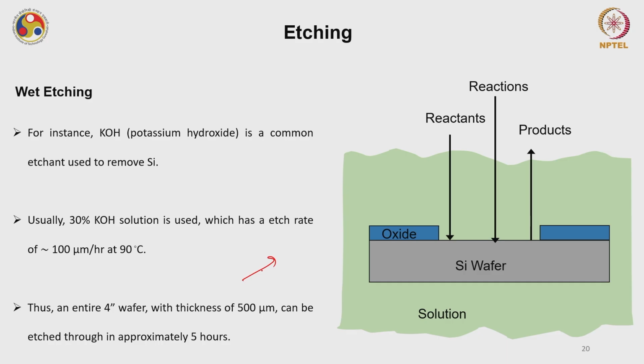So you have to be careful about what thickness of wafer you are using, what the structure is that you want to make, and what the mask is that you are using to protect a particular area. Also please remember that these etchants will have different etching rates across different orientations. Recall the orientations that we studied in our second and third lectures. We have seen N100 wafer, N111 wafer, P100, P111 and P110 and other kinds of wafers